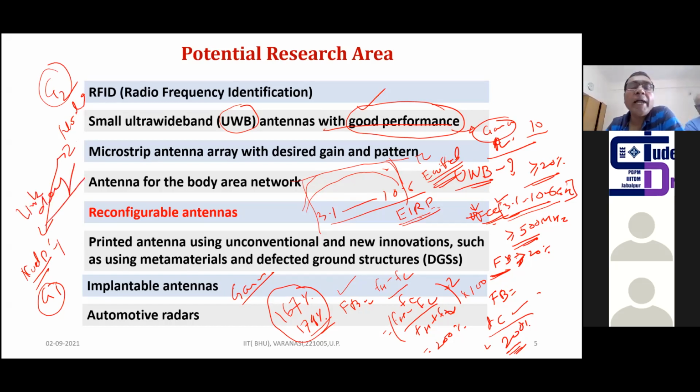So another duty of the antenna engineer is to establish a link design, a link budget. Because of node 2, either we have to design this antenna or this antenna properly. Suppose our node 2 antenna is fixed. We cannot do anything with this one. Then we have to establish a network from node 1 to node 2, and node 2 is fixed. So we have to design the antenna at node 1 in such a way that the gain of antenna 1 meets the criteria of antenna 2.